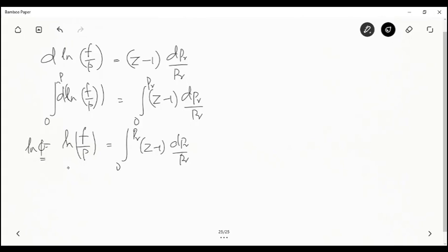So actually you have what is called the generalized fugacity chart. If I know the value of PR and TR, I should be able to read out the value of phi from the generalized fugacity chart, and from there I can evaluate the value of f. Okay, so this is a second method of calculating the fugacity.